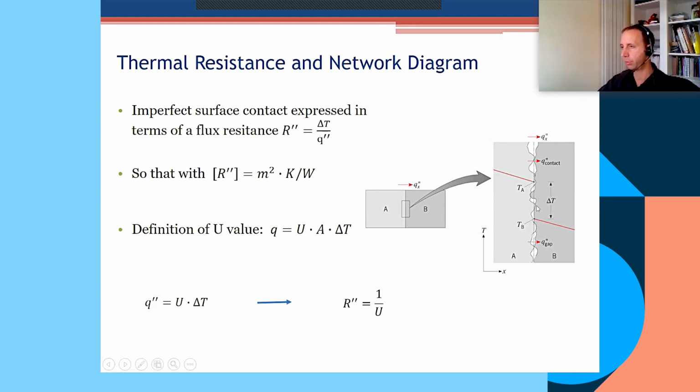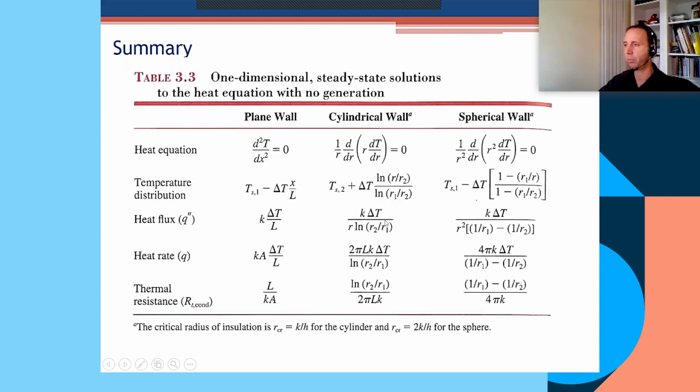You've got cavities, you've got conduction contact, and we can't really resolve all that. So instead, generally, there's an experimental study that tells you for this type of surface, you can expect a thermal contact resistance of that much, and you're given the value for R double prime. So all I'm pointing out here is that most of this data is actually summarized in the table on the first page of your formula sheet, and we'll use it in the context of the tutorial.